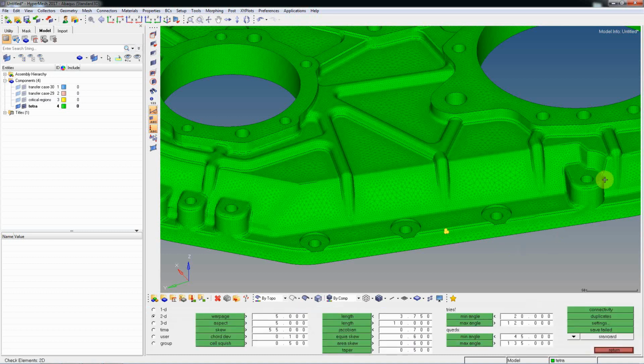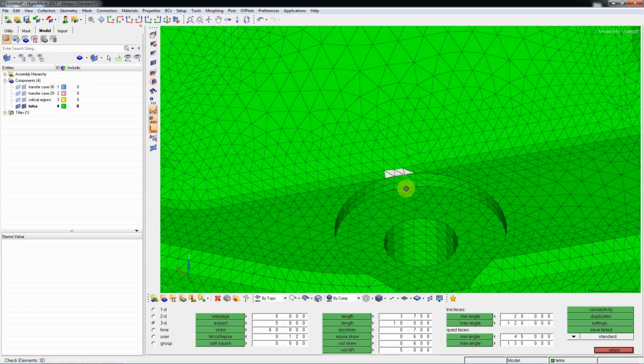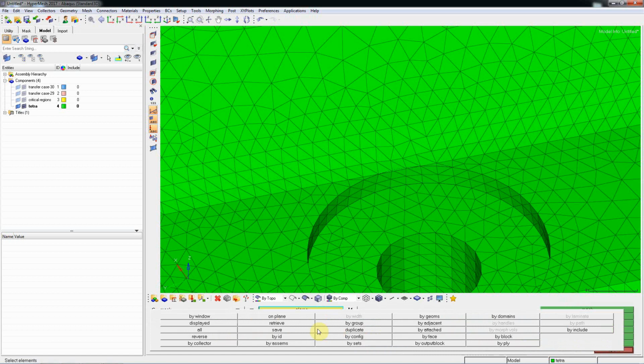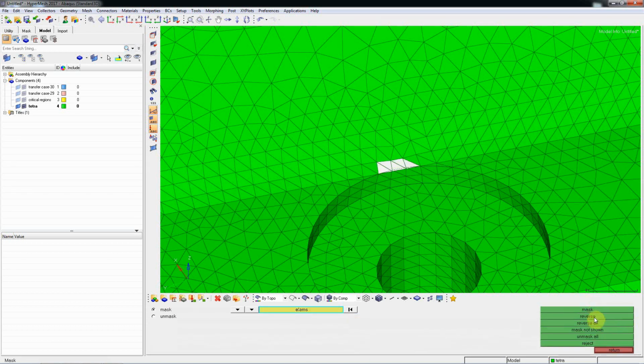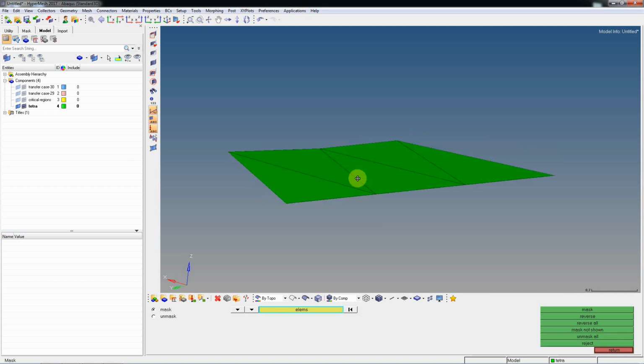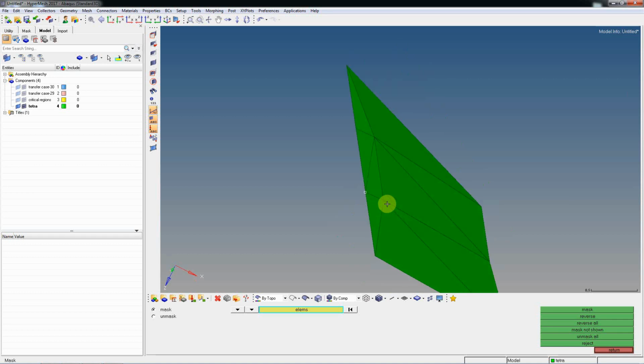Next, we need to go to F10, switch to 3D, and check for TET collapse. I told you 0.12, okay, check 0.12. So around 156 elements have failed because we didn't maintain certain qualities, right? So I'll show you how to fix this. F5, retrieve, mask, reverse, right? So these things are like plate elements. By seeing these, they look like plate elements.